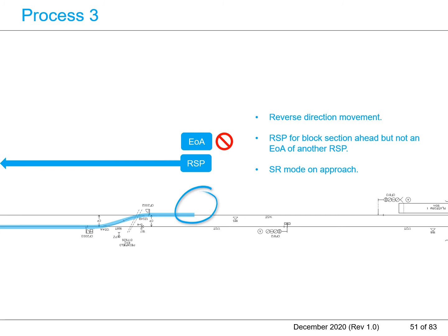via the override function. But moving closer to observe the RSP marker is not an essential operation in ETCS Level 2. When the onboard ETCS receives the movement authority, after the start of mission, the train is authorized to operate in full supervision mode, from the front end of the train to the RSP, and beyond.